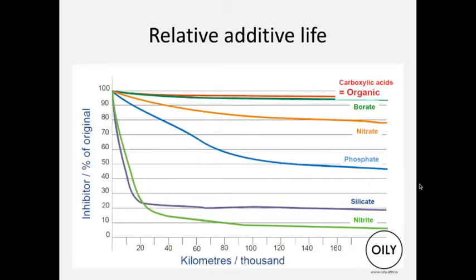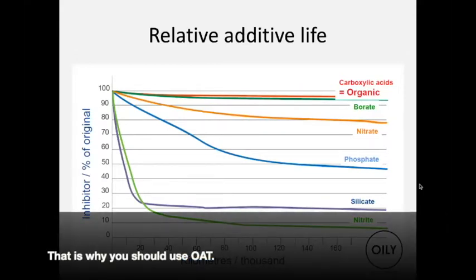The other thing that I didn't stress is Europe typically has hard water. So the antifreezes for European conditions are based on hard water, which drives the big difference between the European and Japanese coolant systems. You should just do OATs.